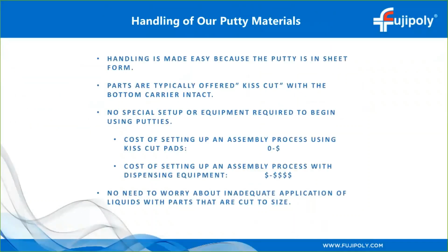Now we'll talk a little bit about the handling of our putty materials. Handling is made easy because the putty is in sheet form. Parts are typically offered kiss cut with the bottom carrier intact. This will eliminate the chances of applying a TIM material with a piece of liner stuck to one side, which would increase the thermal resistance by quite a lot.